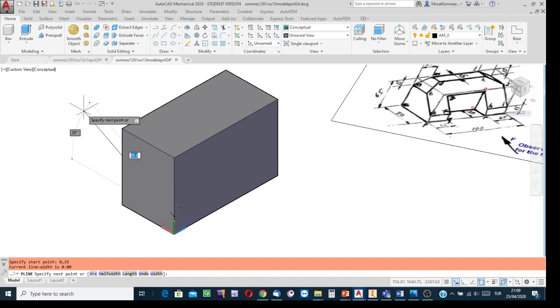Although right now in the simulation I see that AutoCAD, using its default setting, is ready to gather the length of the line and the inclination angle. I don't know the length of the line, the length of the edge of the inclined surface. I don't know its inclination angle. But I know the coordinates of its terminal point. Okay, one coordinate is 35 positive. It is the delta x value.